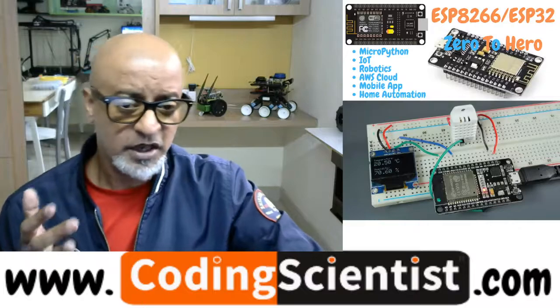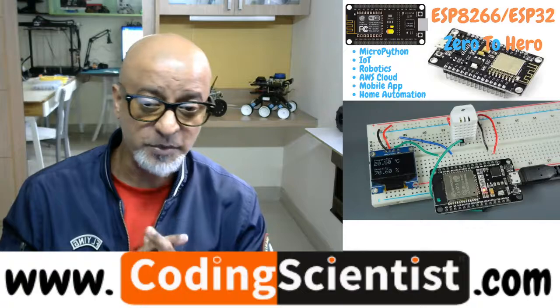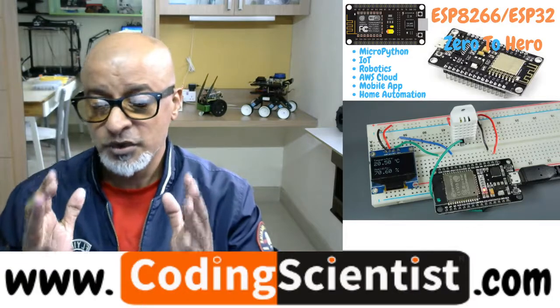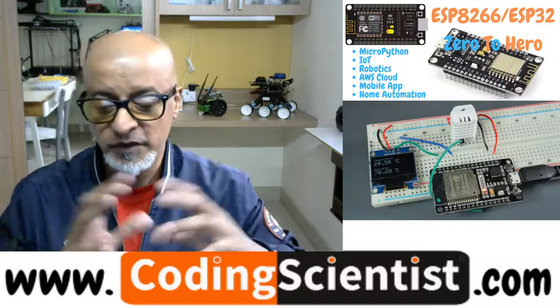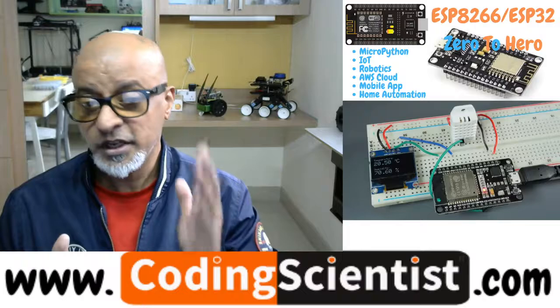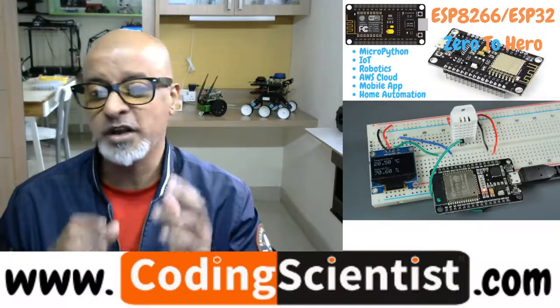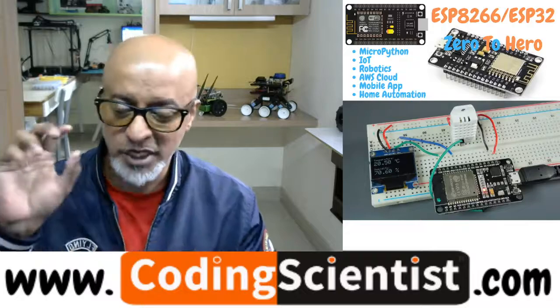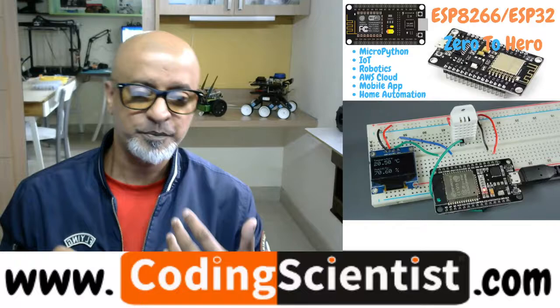As I said, in this particular lesson, I will show you how to build an asynchronous ESP32 web server. I hope you have downloaded the library which I showed you a couple of lessons before, when we were building another project using the web server. If you are not ready, go ahead and download that library. It's on my GitHub. Put it into your Arduino library section where you install, and it will automatically pick it up, right?